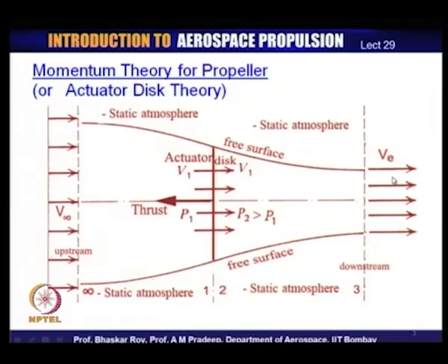How much more depends on the propeller you are using. The general concept that we have used is that the change in velocity across a propeller is normally somewhat small compared to any other kind of jet propulsion. So, this velocity would probably not be very high, and that would again give us another estimate of the thrust, which we shall see would have to be pretty close or equal to the thrust creation determined by the jump in pressure across the actuator disk.